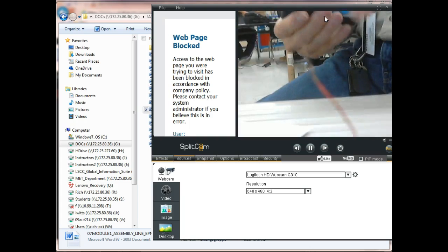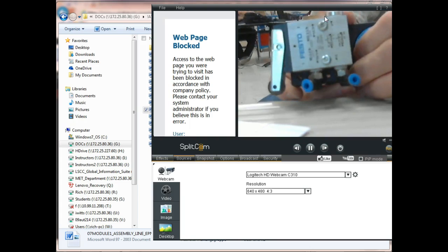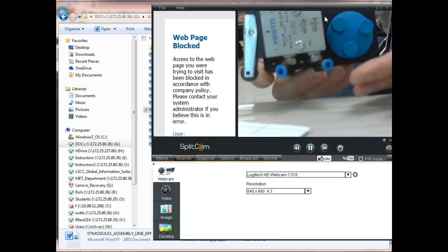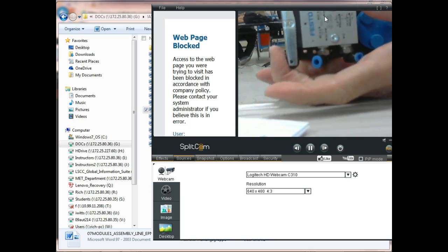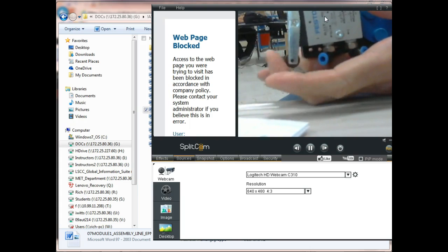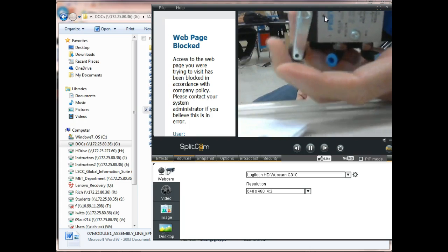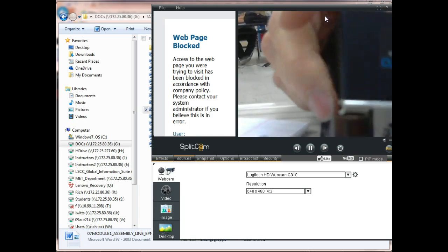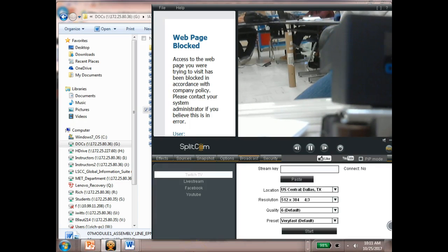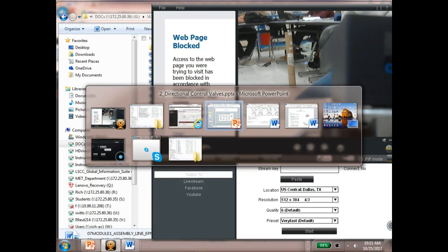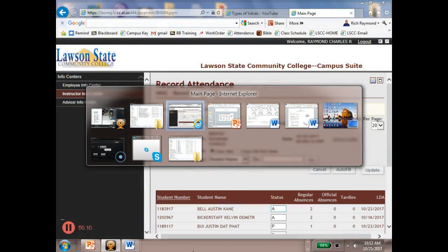This right here would be one that's mechanically operated. So what happens is when something comes over here and pushes on this operator, it actually shifts the spool in there. So that would be this symbol. I'll get to it in a minute. Where's my PowerPoint?